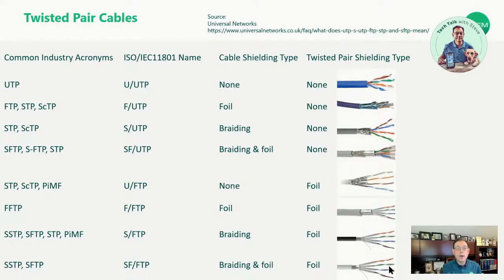But it is good to be able to detect those differences, because if you do run a test, say for instance with our multi-gigabit Ethernet test capability, or even the 1 gig SNR test capability, where you're running a test at, say, 2.5 gig, and you see bad signal to noise ratio levels, you've got excessive noise, it'd be good to run a physical cable test on that shielded cabling, if you do have shielded cabling in that instance, and see: do I have any anomalies in my shield? Are there any problems along the shield where that shield is discontinuous, or has different properties? It changes properties along the shield. So it's always good to be able to look at that.